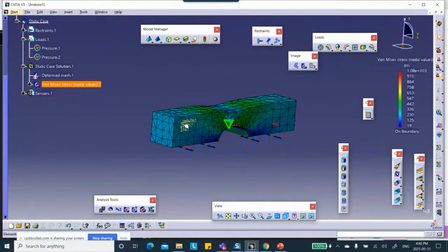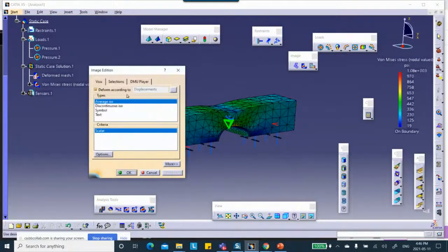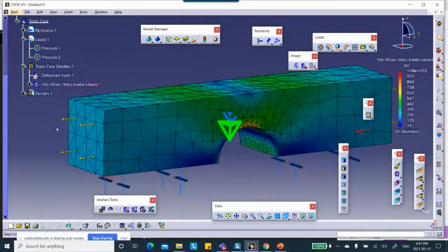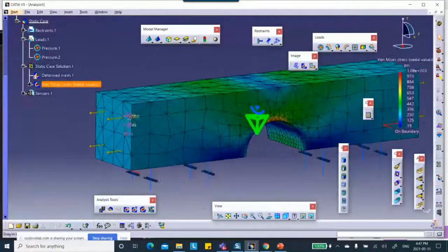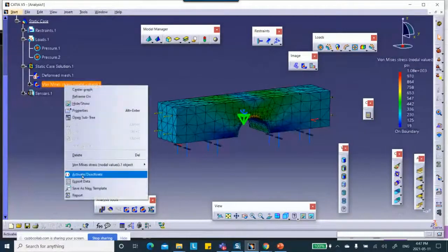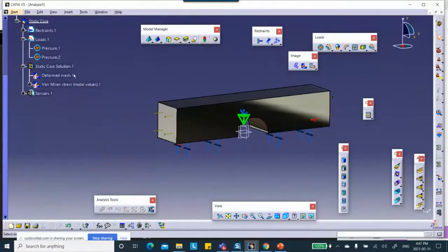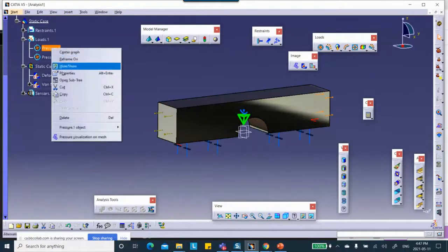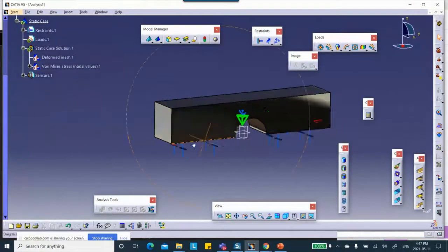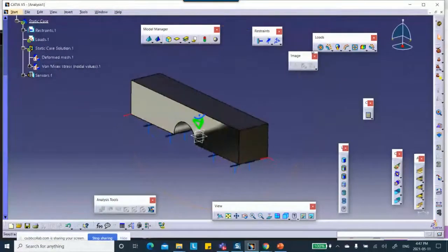By the way, before we go there, double click on this. If it says don't show me the deformed shape, there we are. You can see your pressure here. You see that because it moved and it kind of ate those pressures. Okay, so let me deactivate this. Go and take these pressures away and apply the force. Delete. Delete. Force on this side.